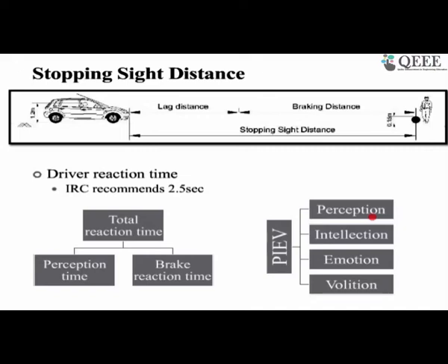In this case, we can have a secondary improvement on the alignment which can help in this situation. One is that you will often see that they put a speed hump or speed bump on the main road, which is again against the natural law. It should not be on the main road but on the side street, because if someone is coming from the side street, they have to first gauge what is happening in the bigger street, and only then enter. So that is what it is.